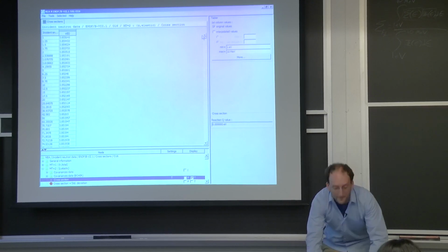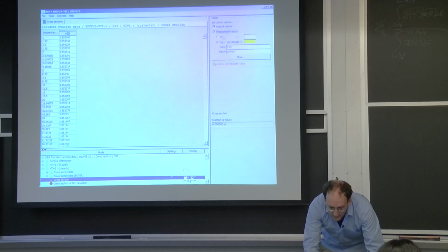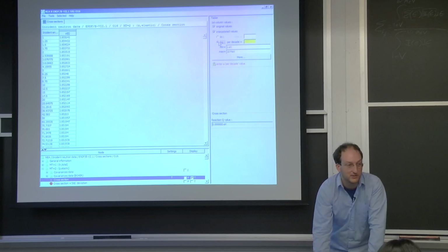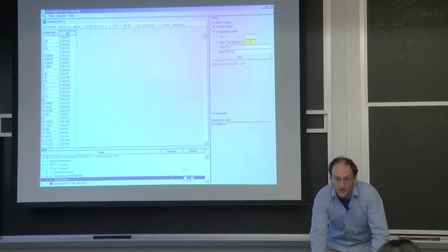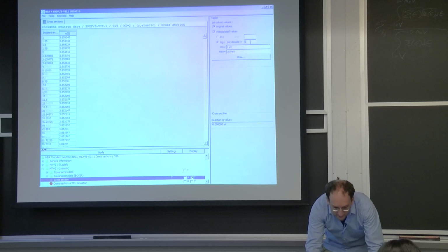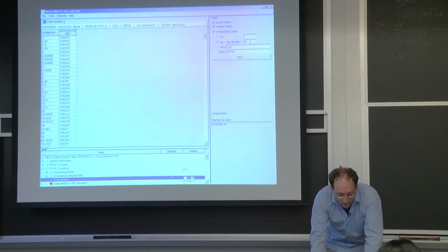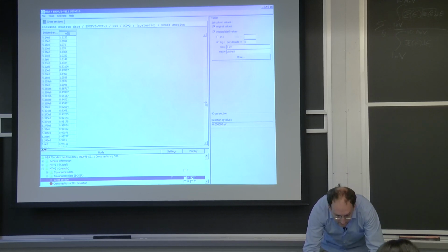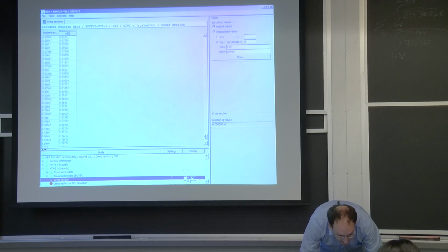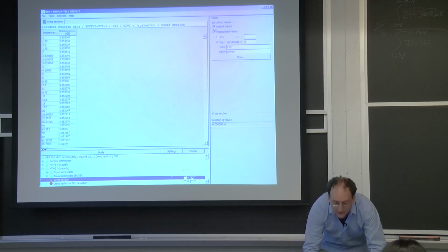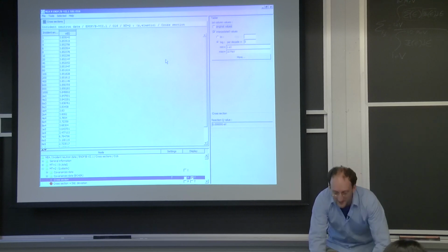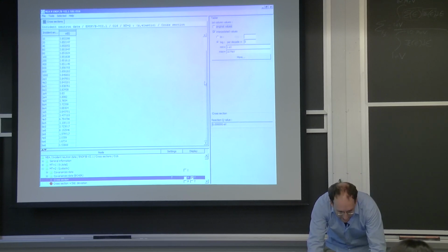Or you can interpolate them. You can interpolate values either linearly or logarithmically. I recommend logarithmic because this is such a large energy range. And get maybe 5 values per decade. So between 1 and 10 MeV, you only need 5 numbers. That's still pretty intense. Oh, I didn't uncheck the original values. Isn't that better? So now there's only 20 or 30 entries.